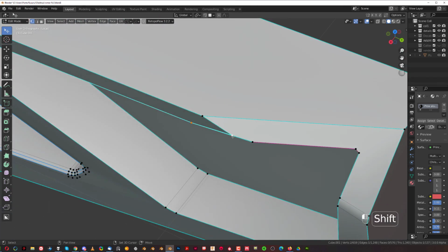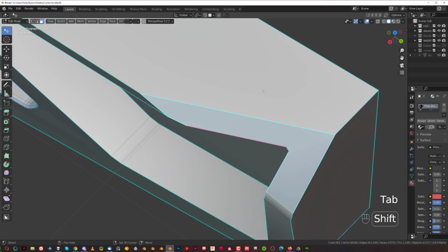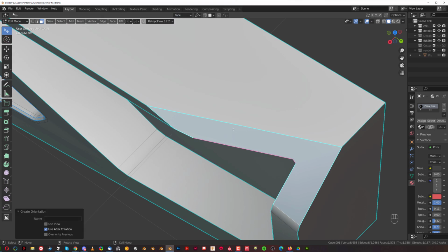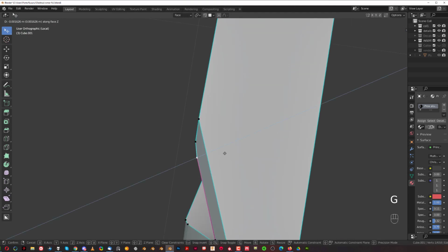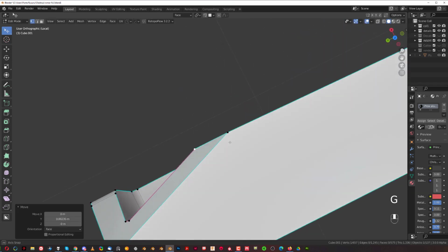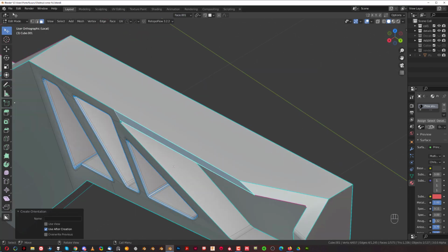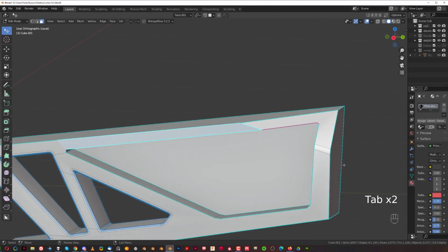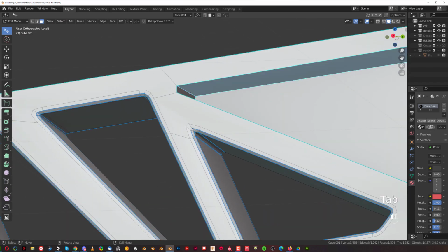So go here and move it like this, and this one should be moving on this axis. So we're gonna grab this face, and we're going to create a custom orientation, and we're going to move this vertice from the top on the custom orientation. So on y-axis somewhere here. And combine these two, and we're gonna align this, right? So GY and move it a little bit to this side. So this one is actually flexed. So change an orientation to a new face, and then SZ and 0 and flex. Boom, problem solved. Cool. Then we need to unchamfer this, and alright, and unchamfer this one, right?